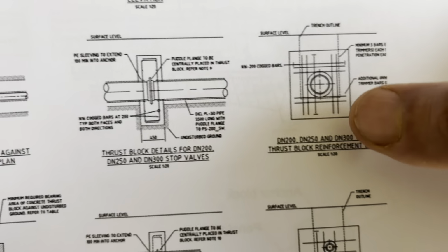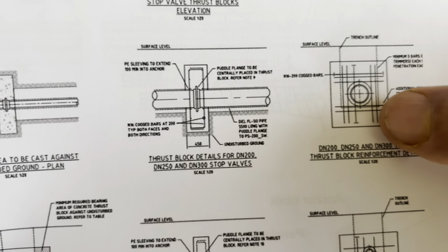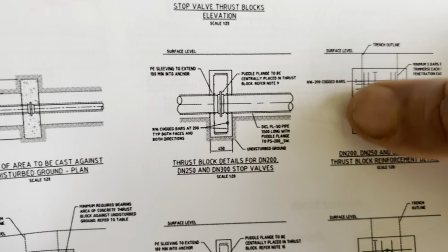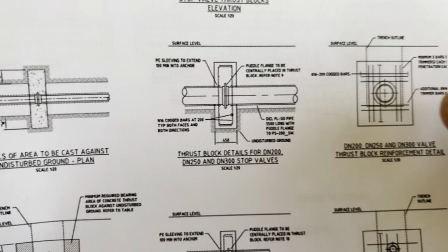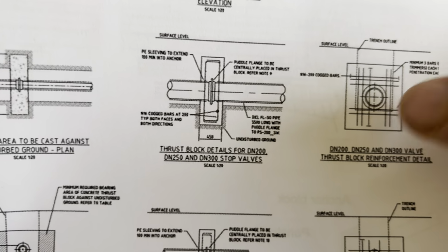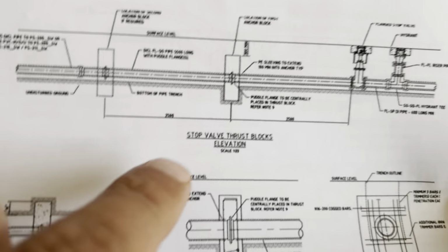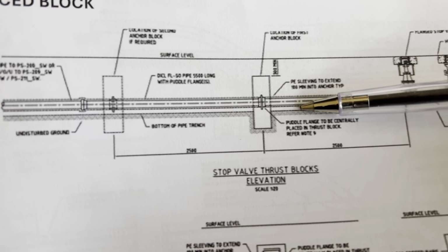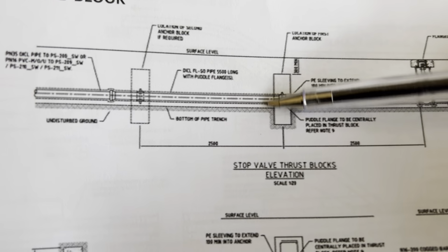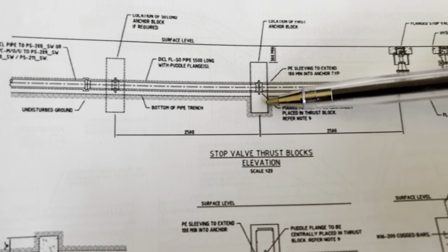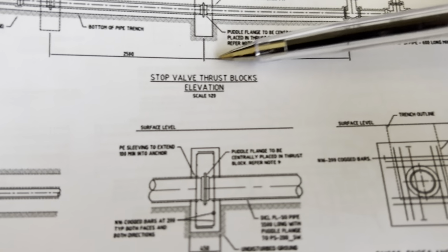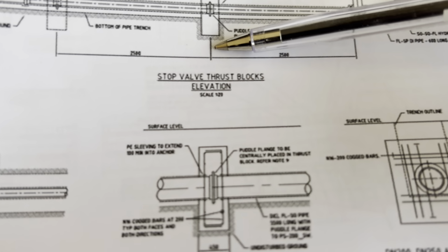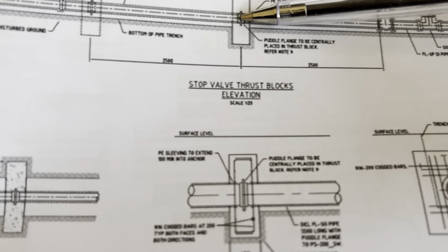This is a cross section of the long section. This is the long section of the pipe. The pipe is here, and around it is a reinforced concrete block that is embedded in the soil. Let's assume that the load is in this direction, and it pushes this system at this point. So we're creating this anchor block like this, and the part of this anchor block that is in contact with soil transfers the load to the soil.